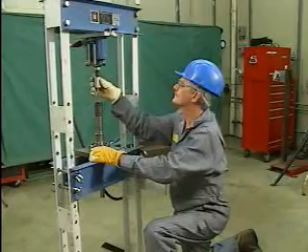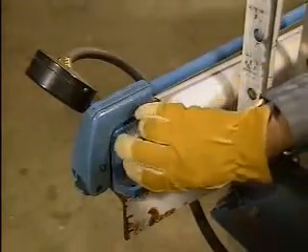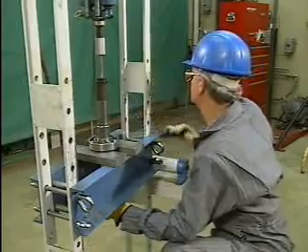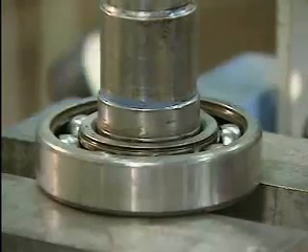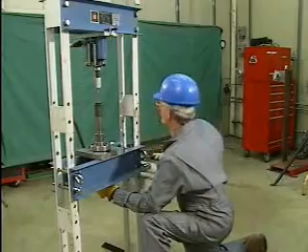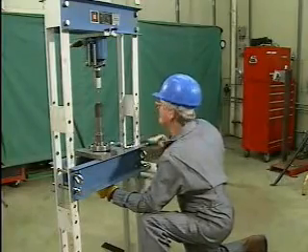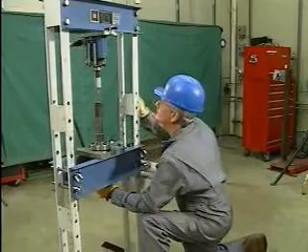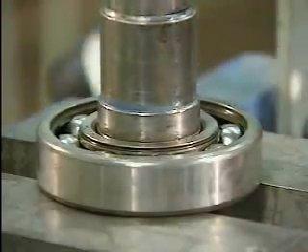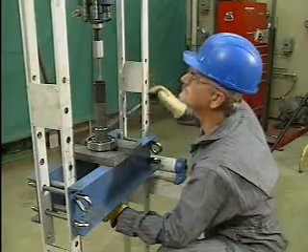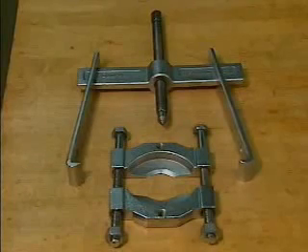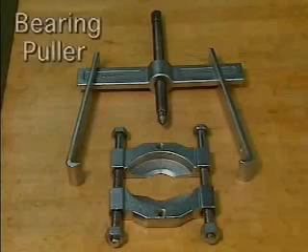After the shaft and the bearing have been lined up, the mechanic closes the pressure release valve on the hydraulic pump. Then he pumps the handle to begin applying force to the press. As the shaft starts to move through the bearing, he watches the bearing to make sure that it does not jump off its supports and to make sure that it is not cocked. If the bearing is cocked, it will jam on the shaft. As the shaft is forced straight down through the bearing, the mechanic holds onto the shaft with one hand to prevent it from dropping.